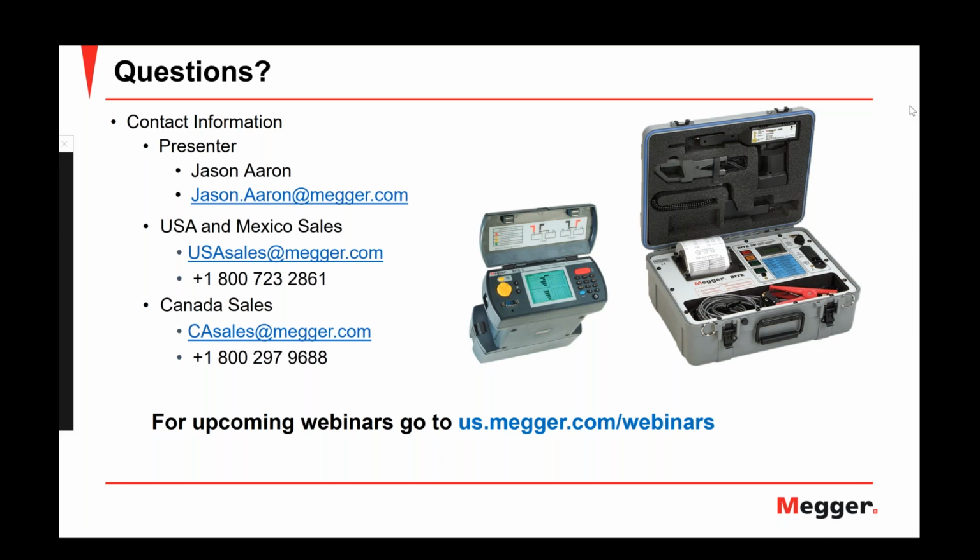There's also standards for the proper installation of these batteries, 484, 485. We'll talk about lead acid, vented and valve regulated. The worst enemy of a battery is temperature. So temperature is the worst aspect that you can have, increased temperature in a battery environment.